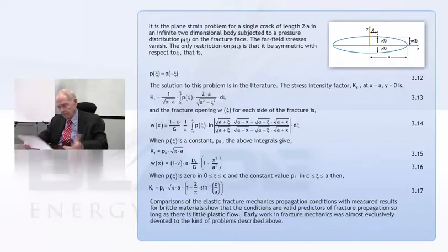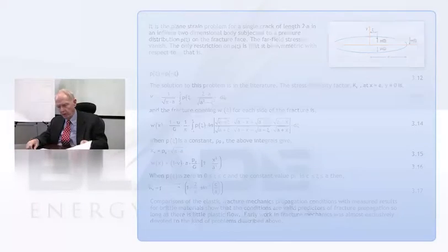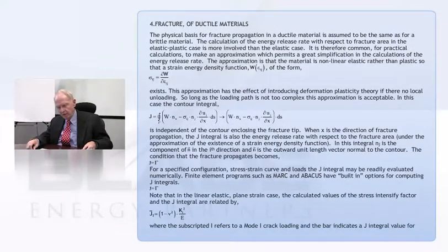And this isn't, of course, the only problem that's been solved. There's a book that has nothing but solutions of these kind of problems with singularities, and it's a handbook, and I think you can find it in any engineering office that's doing anything serious about fracture mechanics. Okay, so now we need to try to cross this bridge to the case where we have some plasticity in the problem. And that's on the next slide that starts with the fracture of ductile materials.